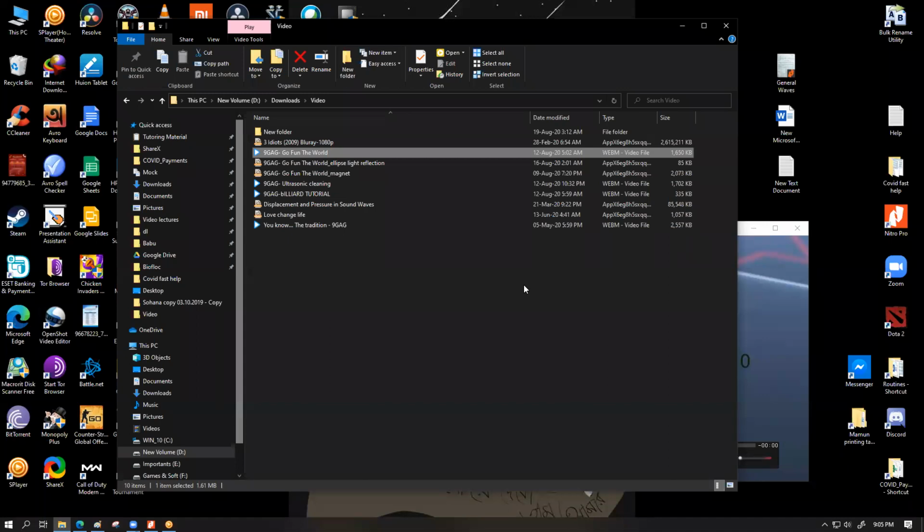That water was being vibrated at ultrasound frequency with some mechanism that is placed on the side or the bottom of the container, and that fluid had some very microscopic particles which could work as an abrasive. That's what this blue fluid was all about. Once you place it over here and turn on the ultrasound, all the fluid vibrates at ultrasound frequency.